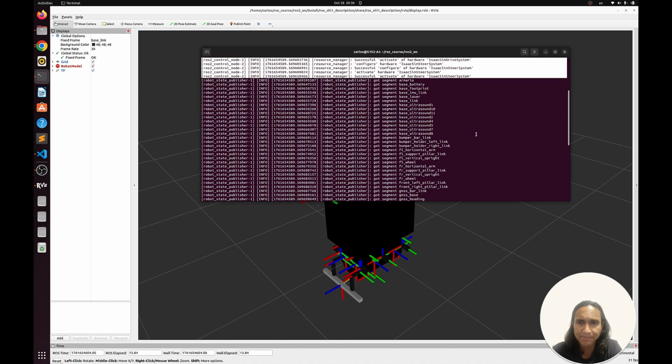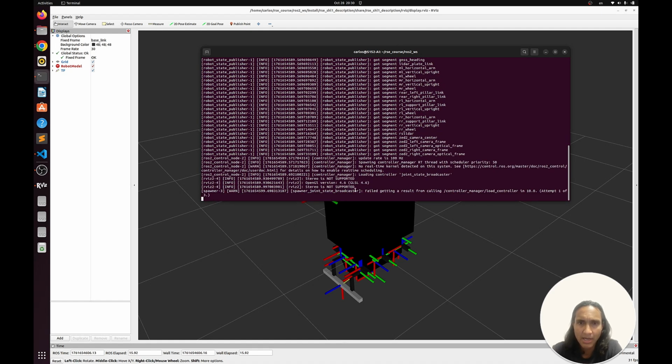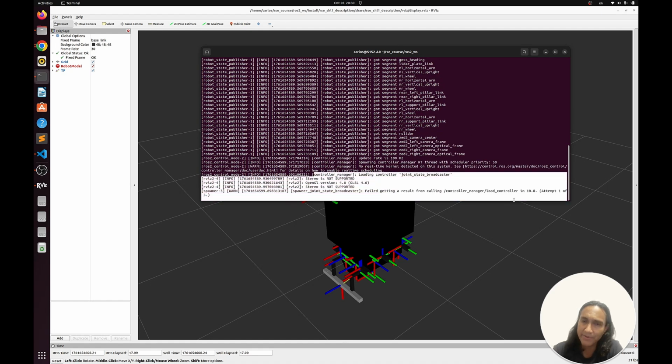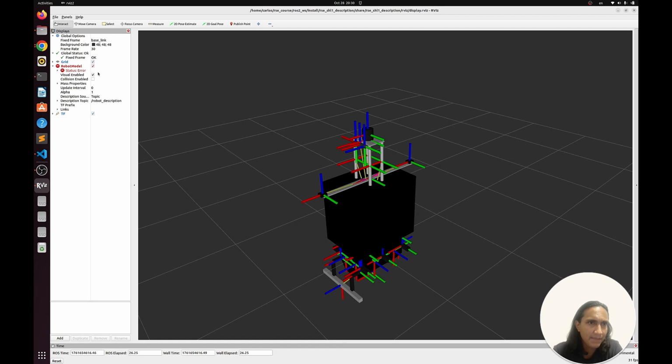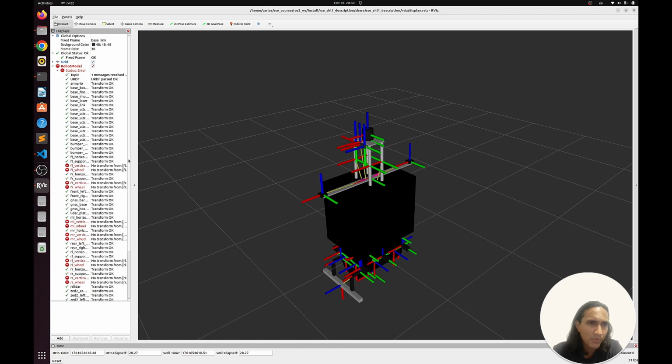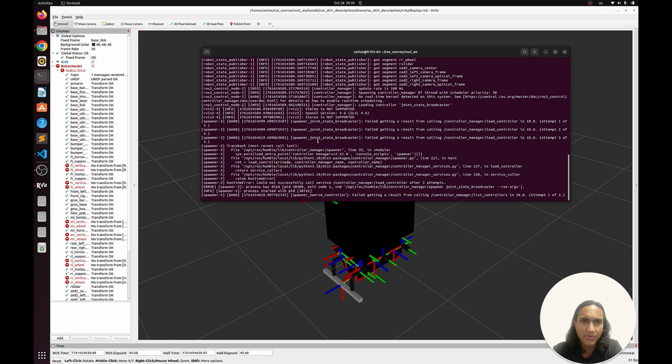One for the steering, we're going to see that later. But look, there's an error here. Obviously there's an error. If you look in RViz, there are no wheels, and the robot model section is complaining that we don't have all of these wheel joints. Of course we don't, because our simulator is not running. Isaac is not running, so we don't know what's going on with those joints.